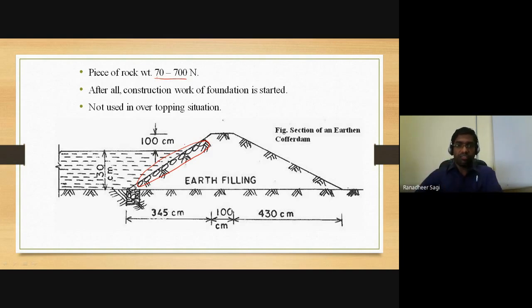If the weights are relatively high, because of the excess weight the stone particles might cause sliding failure in that slope of the embankment. If the weight of the aggregate particles is small, then sudden wave forces cannot be taken care of by the aggregate particles, which are relatively of smaller sizes.